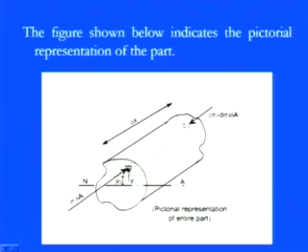So we can simply visualize that when these fibers are influenced in both ways, the resultant comes from this side as sigma into dA, that is the force, and on the other side sigma plus delta sigma into dA. We are saying that this small element is in equilibrium, so whatever forces are coming will cancel each other, and that's why the complementary shear stresses, tau, also come, all across parallel to this cross section, or we can say parallel to the fibers, and that's what we assumed in the previous section.